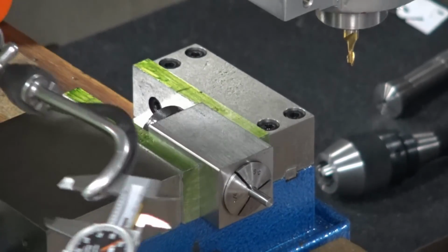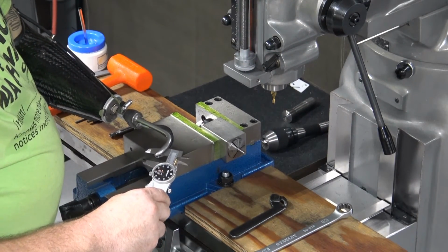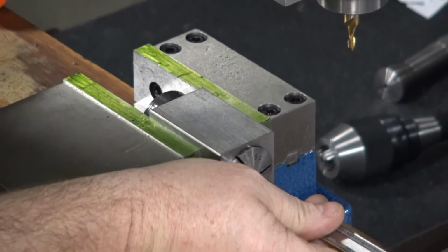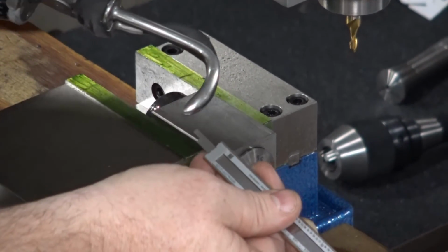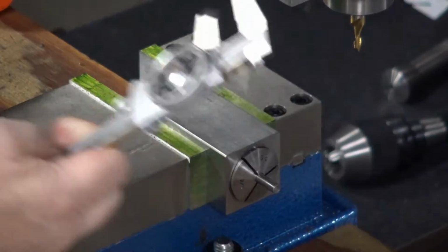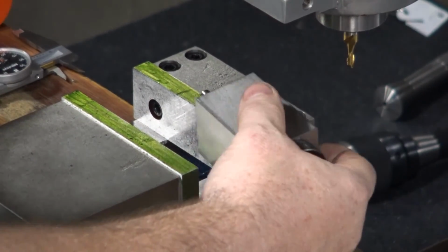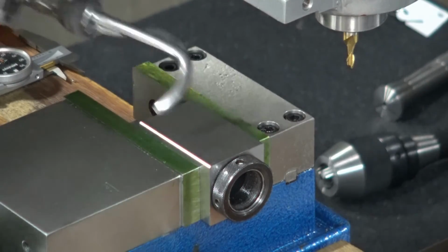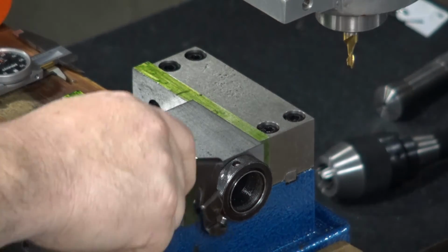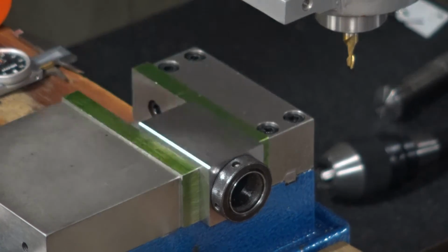So I'm going to take my calipers and set them to 650. That way, it's plenty long enough sticking out that I don't have to worry about machining into my collet. Right? We're going to use the tail end, 650 thousandths. Make sure I've got enough stick out. Done with my calipers. I'm going to spin this guy around. I'm going to thread that collar up on, lock it into position. Let me go ahead and crank this guy out of the way.